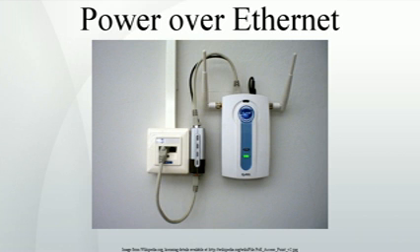A typical 48-port Ethernet switch has a 50 W to 80 W power supply allocated for the traditional Ethernet switch and transceiver IC. Over and above this it requires typically a 740 W, for 802.3af, to 1480 W, for 802.3at, power supply allocated solely for PoE ports, permitting a maximum draw on each. This can be quite inefficient to supply through long cables. However, where this central supply replaces several dedicated AC circuits, transformers and inverters, and prevents expensive human interventions, AC installations, the power loss of long-thin DC cable is easily justifiable.